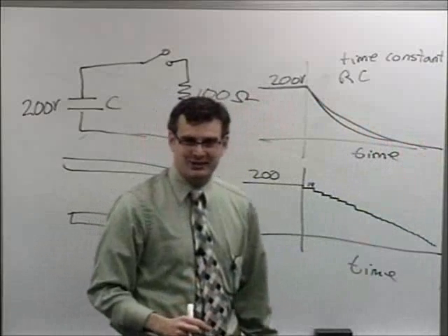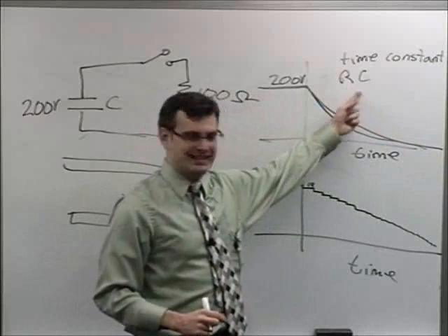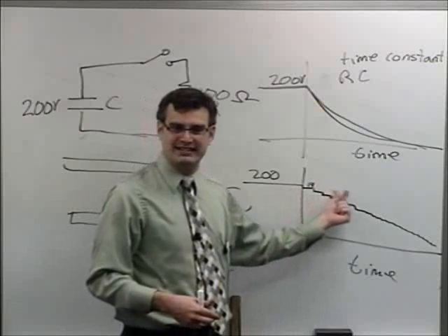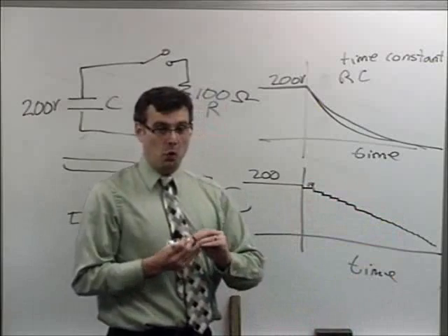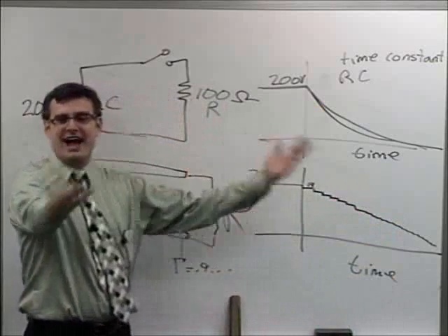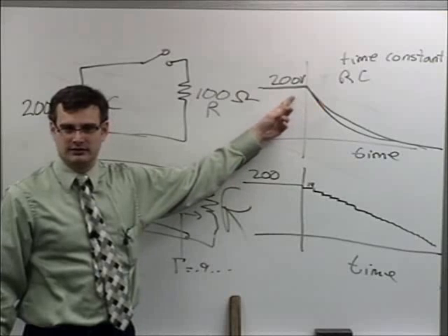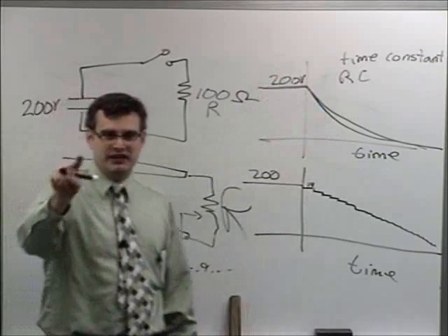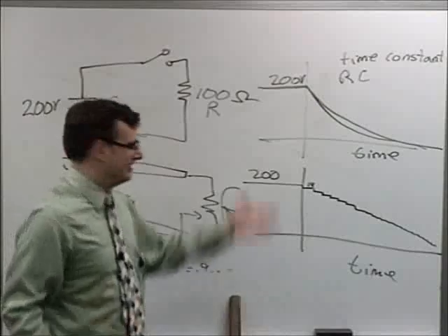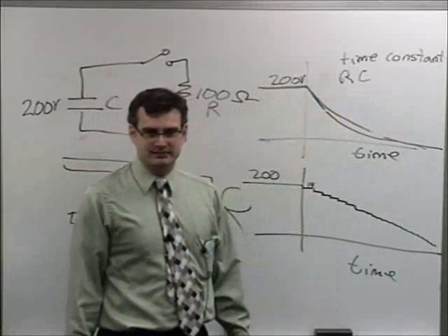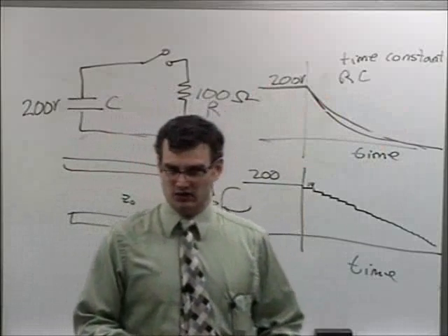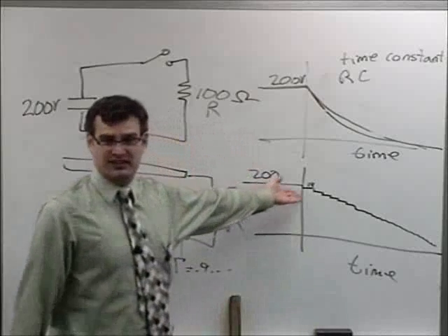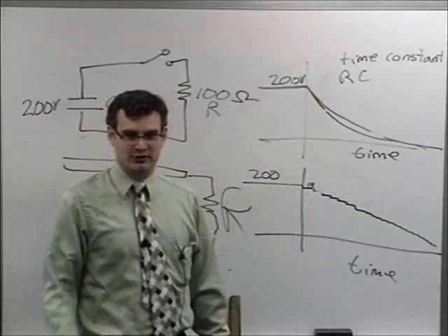And if you work through the math, it turns out that the time constant for this thing is related to the reflection coefficients times the little transit times that are discharging. And from one time scale, this capacitor problem looks exactly like your RC circuit. In fact, it will be unlikely that your sibling's finger is perfectly matched to this particular transmission line. This will much more likely be your transient. It's interesting, though. You probably didn't know that about your capacitors. There are these weird discrete modes of discharge that exist on them, and you would never see them with any of the cheapo oscilloscopes in your 2040 lab or 3040 lab, or 3041.